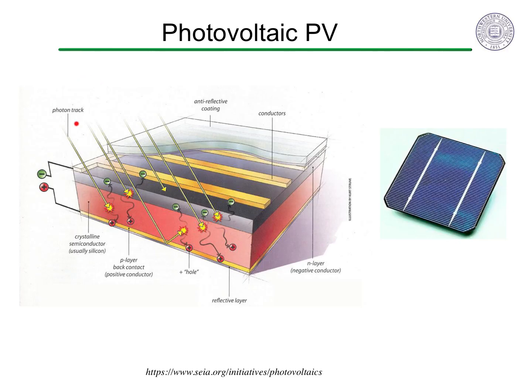In a photovoltaic, sunlight is absorbed, creating electron-hole pairs. The electrons are collected by the top, negative electrode, while the holes are collected by the bottom, positive electrode. What we see from the outside is the anti-reflection coatings and finger electrodes to maximize and not block the incoming light. Inside is typically a single crystal silicon p-n junction diode that helps separate the electrons and holes.